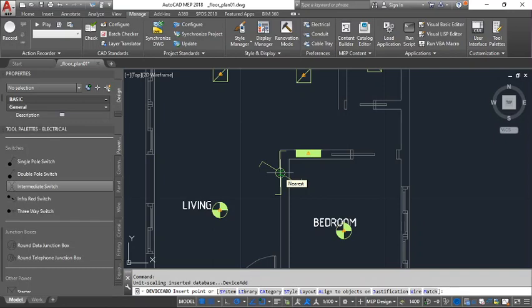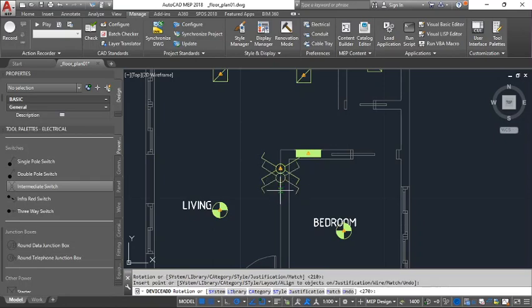They think 2-way means 3-way, but it's a mistake. Actually, the normal switches that we use are all two-way switches, because you can either switch on or off, so those are only two ways. With three-way you can switch on, off, and then there's a third in between that enables the other side to be switched on or off. That's why it's a three-way.